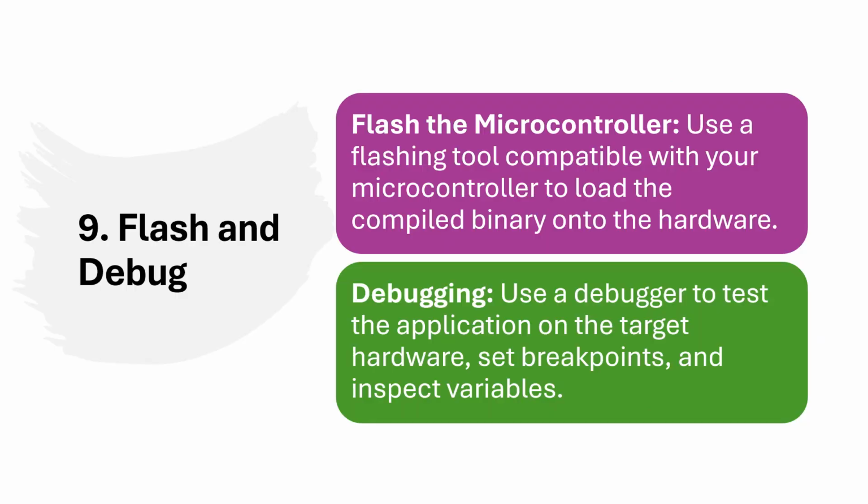So flash and debug. Flash the microcontroller using a flashing tool compatible with the microcontroller to load the compiled binary on the hardware, and debug using a debugger to test the application, test the hardware and set breakpoints. For example, when I was working on a car steering system, once I flashed the software on the motor or hardware, then you can connect it with different debugging systems